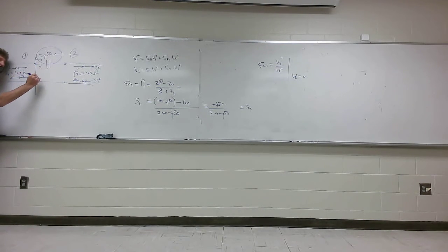I'm after the voltage just on the other side of that transmission line. Remember, the voltage just on this side isn't this because there's a reflection coefficient. Some of it's reflected back. The sum of the reflected voltage and the incident voltage is the transmitted voltage. So here it would be a transmission coefficient at port 1 times V1 plus, correct?